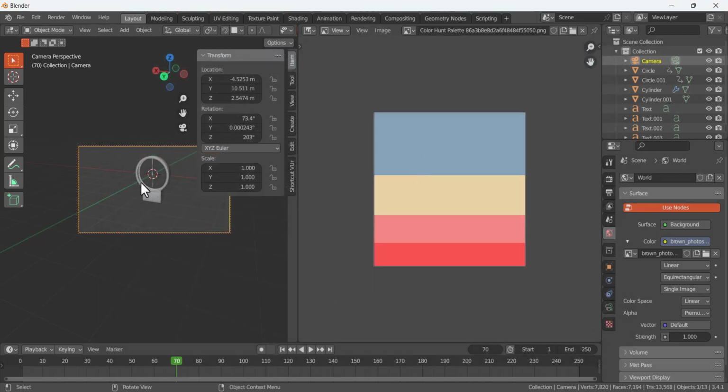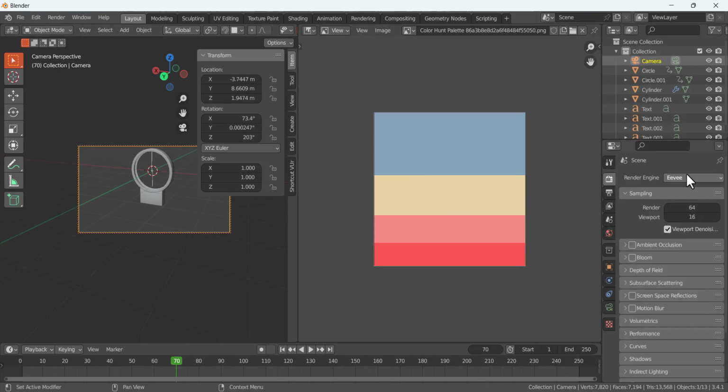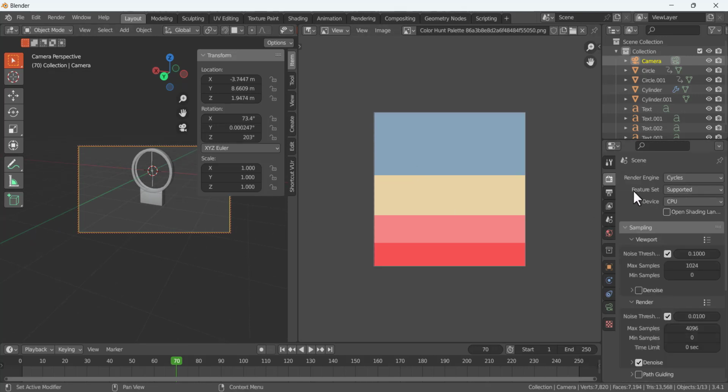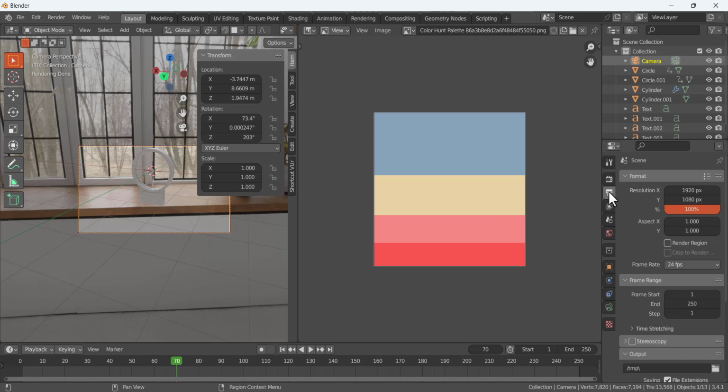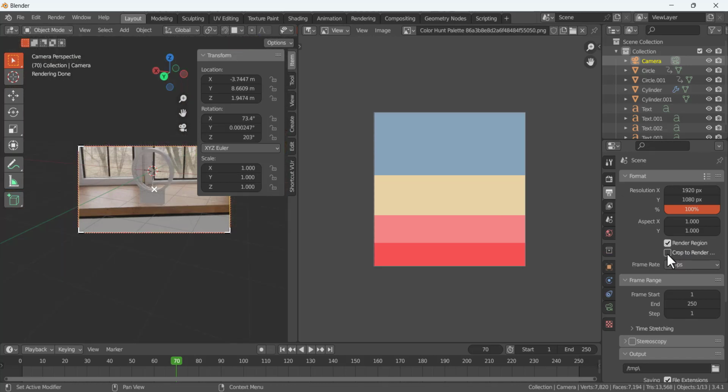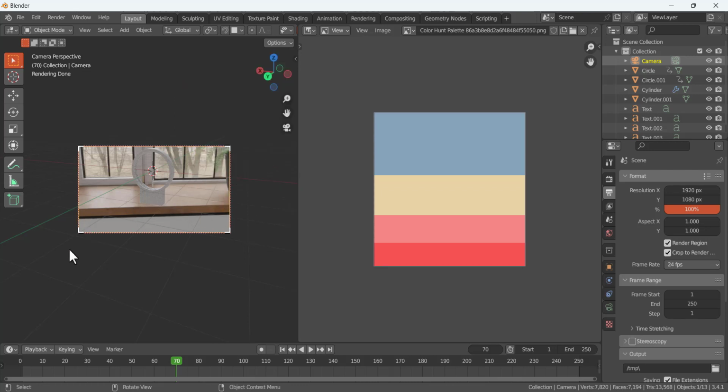Basically, I'm going to select the render engine Cycles, and here press Z. So you go to the render like that, and under the output properties, I am going to enable crop to render, so we only render this view. I am going to type N to hide this one. Control B to select the area of your render. So now it will only render this one.